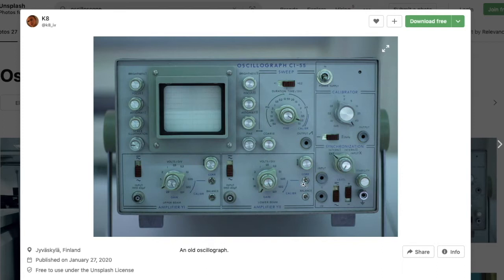If your oscilloscope has two channels, then two different voltages may be displayed simultaneously for direct comparison. So oscilloscopes can basically measure the frequency of oscillating signals, circuit noise levels, period and voltage values of signal waveforms, phase shift of one signal relative to another signal. We can also check whether an interference disrupts a signal. And finally, through oscilloscopes, we can determine how much signal is AC and how much signal is DC. We will discuss its basic controls later, but for now, let's peek inside an oscilloscope.